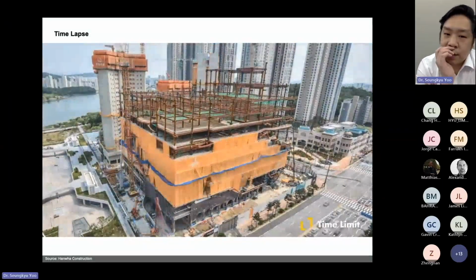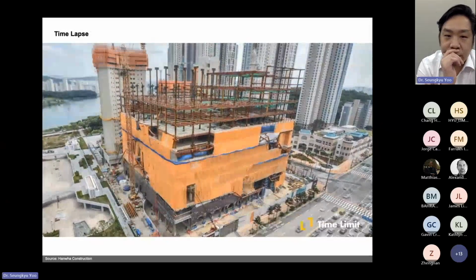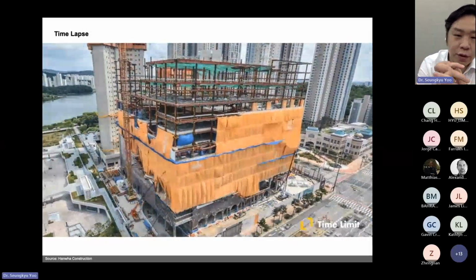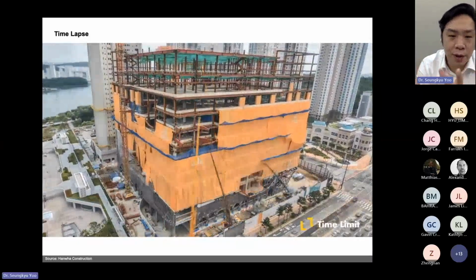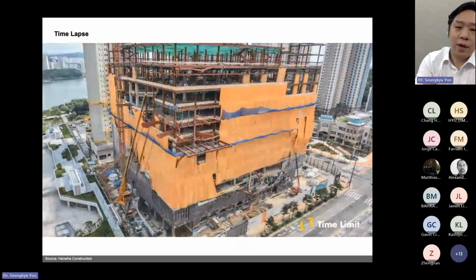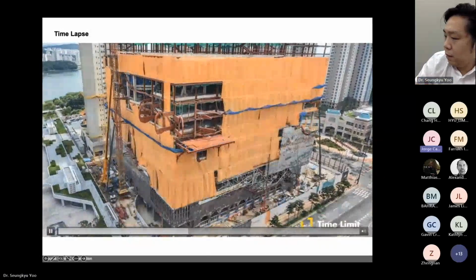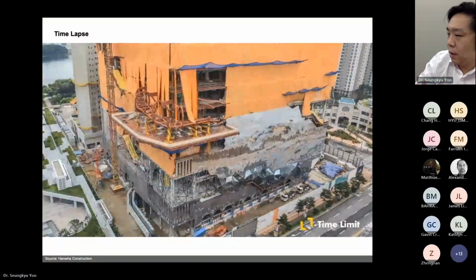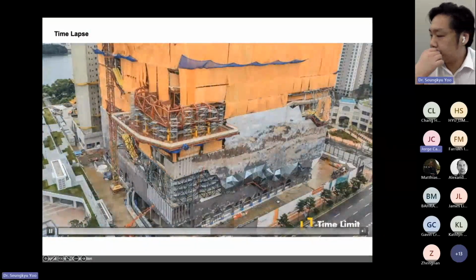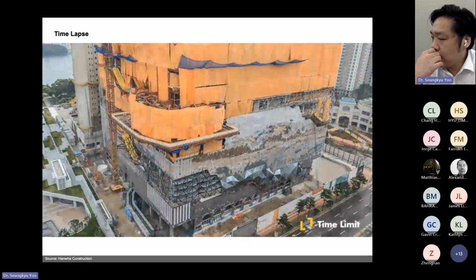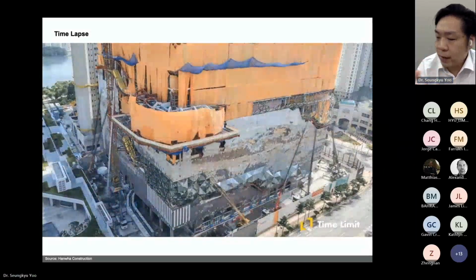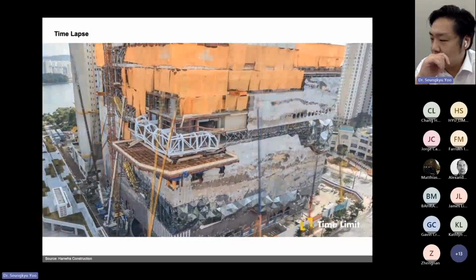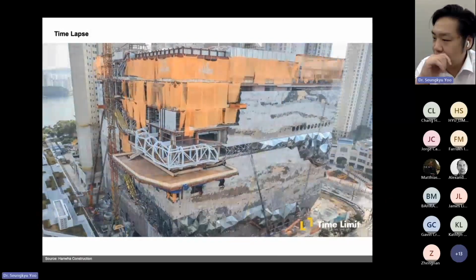We utilize the 3D scanning process to minimize the construction tolerance of fabrication and on-site lifting, and to attach the facade modules. We lift the facade part modules one by one, and then we check the glass panel size, and then we can easily order from a Chinese glass company, and we can match the construction duration.